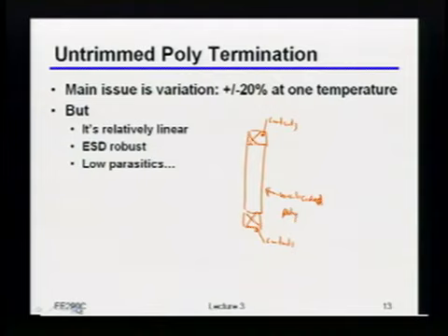Now, in some links, that's probably okay. It's probably good enough, right? You just say, okay, I'll measure my link with the worst case termination resistors and make sure things actually work there, right? But sometimes when you're really pushing the edge of what's feasible, you really can't tolerate that plus minus 20%. You really need to bring that down even tighter to make sure that you've got that last few millivolts of margin that you needed to make the thing actually work.